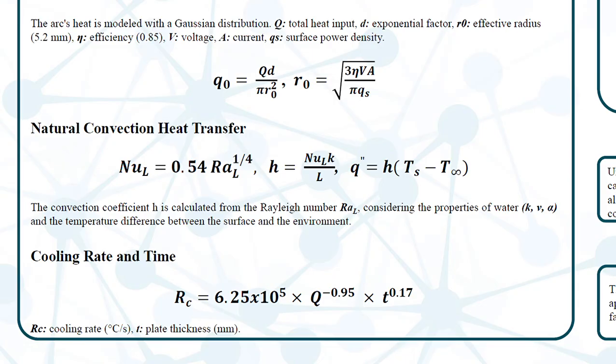And for the cooling rate equation, finally we use an empirical equation to calculate cooling rate. This equation was proposed by Suga in the late 90s, and recently was retaken and applied in underwater welding, and specifically in this type of process as flux cored self-shielded FCAW. Together, these equations allow us to simulate the temperature profiles, the peak temperatures, and the cooling rates of, in this case, the welds.